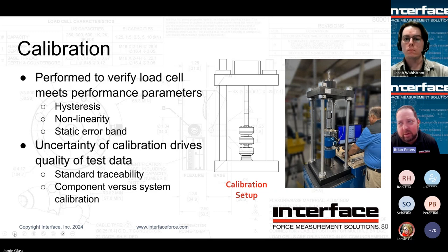Or if you have the scenario where you have a thermal gradient being introduced, say through the load string, that may take time. Again, if the load cell doesn't stabilize thermally, then yes, you could have some less than complete thermal compensation happening from a bridge standpoint. So just for reference, if it's an LP we're talking about, most of our thermal compensation is going to be done for the zero balance, at least behind our label. So pay attention to that. You don't want to have anything hot shooting right at our label. That's not going to allow the thermal comp to work as best it can.